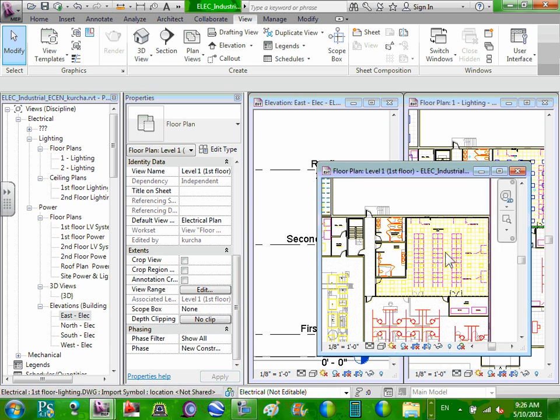Now those modeled elements will still be in here, but now you've got to set up your workset visibilities, apply your view templates, get all your annotation over, because annotation doesn't bleed through. It's only on the view that you apply them. So there's still a lot of work to correct it that way.